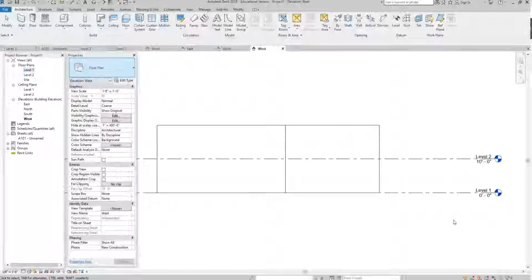And a floor plan is defined as a horizontal cut 3 to 4 feet above the actual level of the floor plan, right? So what that means is if we were in this room and you were to view a floor plan of this room that we're in, you would be viewing it as if you had cut the floor plate at 3 to 4 feet, horizontally. You were to slice it and take everything above it off, okay? And you're viewing looking down. That's what a floor plan means. A horizontal cut across the building at 3 to 4 feet, and you're viewing downward, all right?